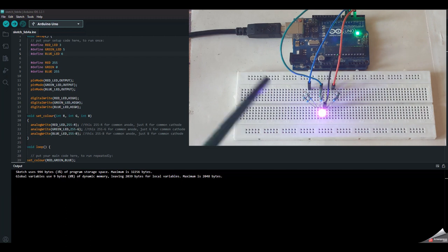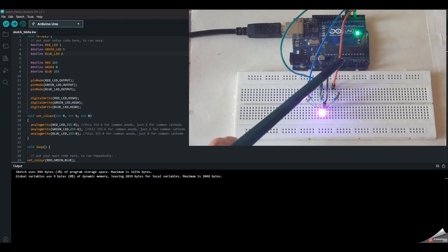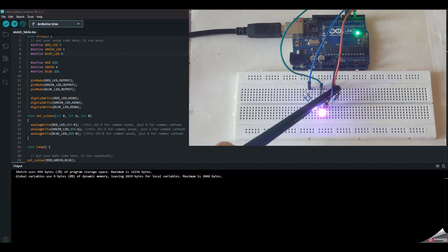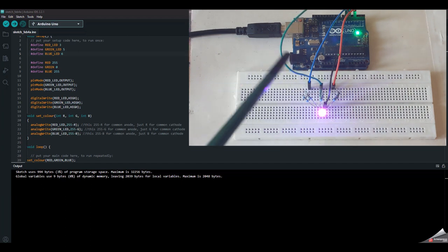But please note that if we are using that kind of approach, we need to make sure that we have connected the resistors across these connections, because there may be a chance that the two ports may be shorted, and the resistors are absolutely necessary. So make sure that you have connected the resistors and then proceed further.